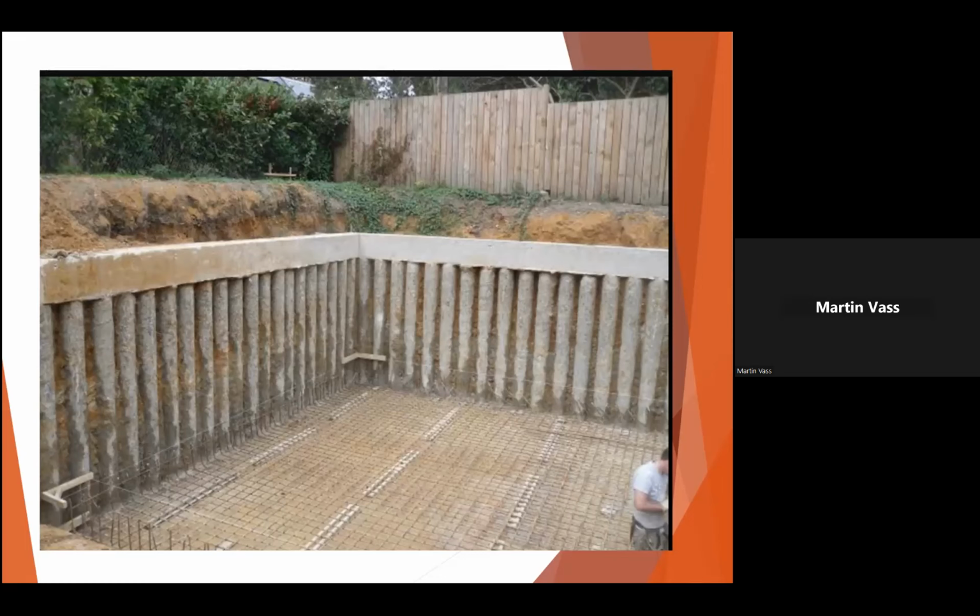Lateral support, we have a lot of claims on lateral support, where support is removed from the adjacent property. And lateral support, in fact, is strict liability. You're not allowed to affect the adjacent property. So any damage to the adjacent property is strict liability. You are liable. So you would put these piles into the ground and then remove the ground inside the piles.